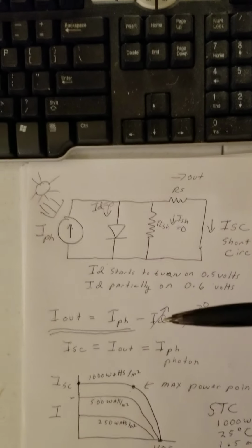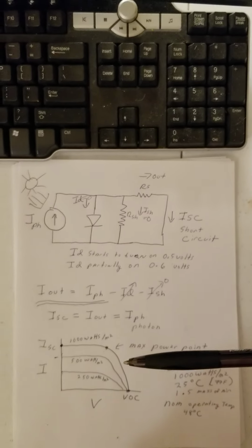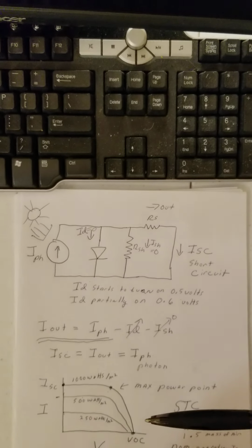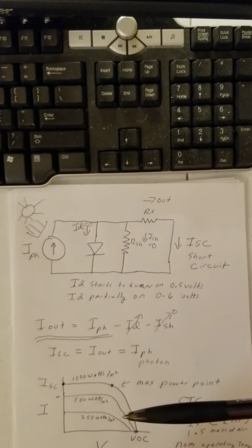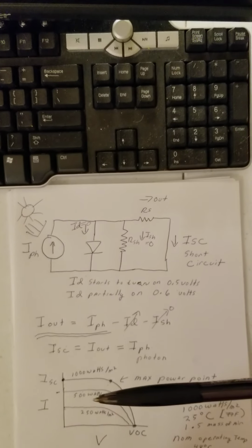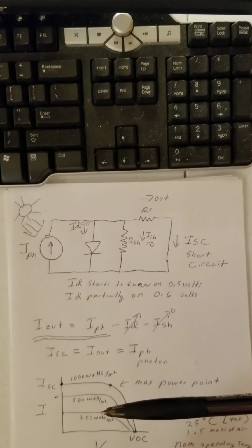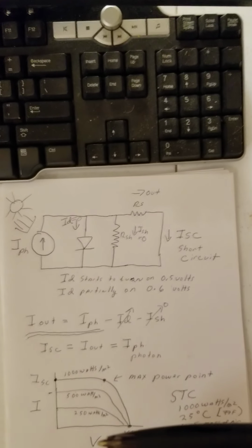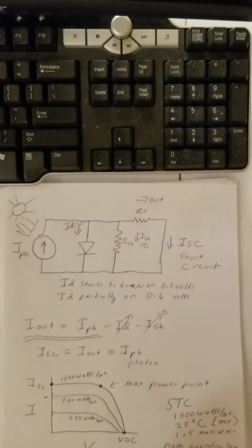Okay? And what surprises people is that in the wintertime, the open circuit voltage gets larger. And that's important for selecting charge controllers. And in the summertime, the open circuit voltage actually gets smaller and reduces your output power in the summer. And that's enough for this video.